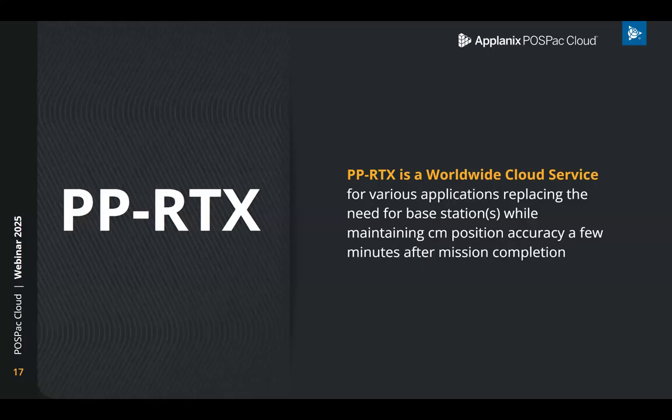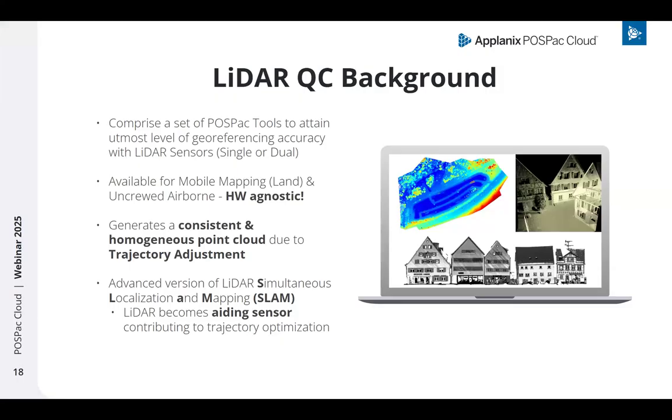PPRTX is a worldwide cloud service for various applications, replacing the need for base stations while maintaining centimeter position accuracy a few minutes after mission completion. Another core feature is the LiDAR QC. Applanix LiDAR QC tools comprise a set of POSPac software tools designed to attain the utmost level of georeferencing accuracy with the LiDAR sensors. Primarily employed in the uncrewed airborne, land mobile, and indoor survey industry, this software is hardware agnostic, functioning seamlessly with any LiDAR system.